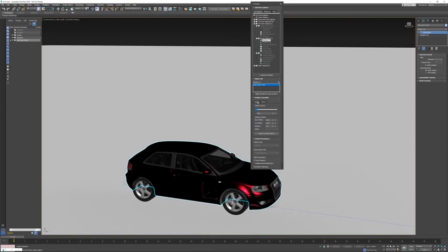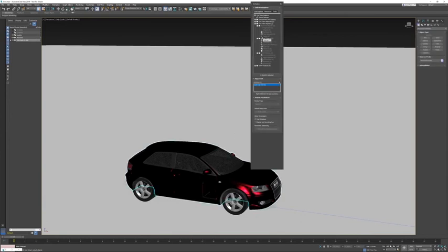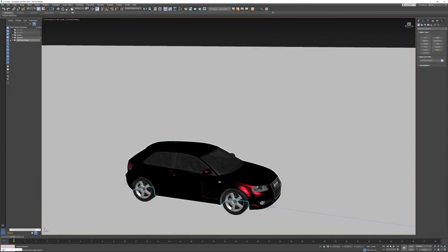And in the tracking tab, I'm gonna disconnect the position controller. So in the background, it's just using a path constraint, and I'm disconnecting this one. So by hitting the X, it's gonna ask me, are you sure you wanna bake the position? Gonna hit yes. Okay. And now I'm able to select the vehicle itself, including the front and back axis.